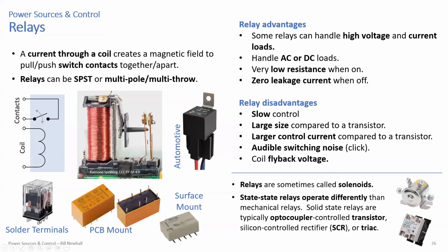Well, relays do that same thing. So if you were using this relay, maybe this relay is controlling a load, you're trying to count how many times the load is turning on and off by looking at the load power, the load side of this, the contact side. Well, then you could get bouncing. So you'd have to write, in software, there's some code you can do with a delay to mitigate switch bouncing as seen by the microcontroller. Or you can put a low pass filter and handle this in an analog way on the contact side. But that would be a disadvantage. You can get bouncing seen at relay contacts.